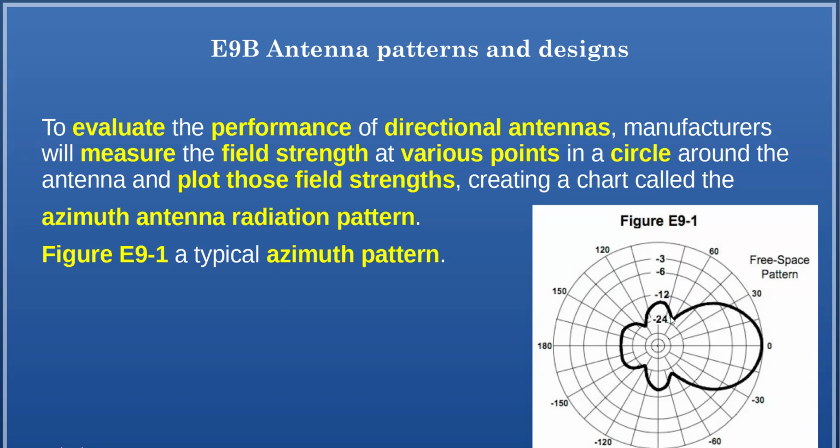One of the side effects of maximizing gain is you get more side lobes and maybe a larger rear lobe. So one of the things they play with is the spacing of the elements on the Yagi and the length of them, which affects all these kinds of things and gives different patterns. Sometimes you don't want maximum gain.